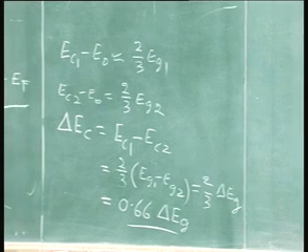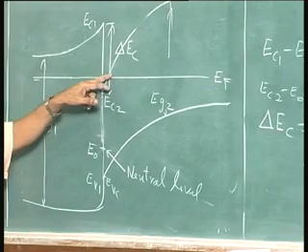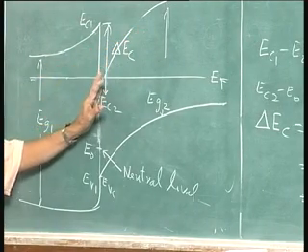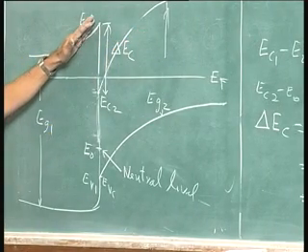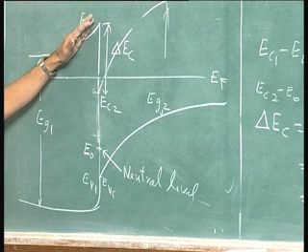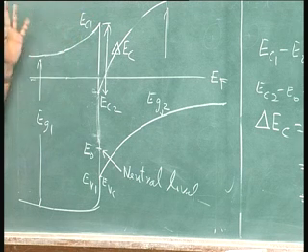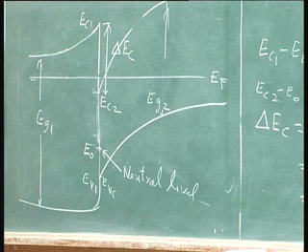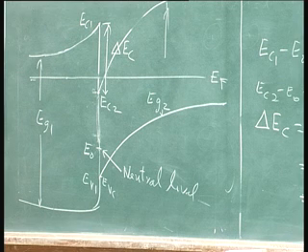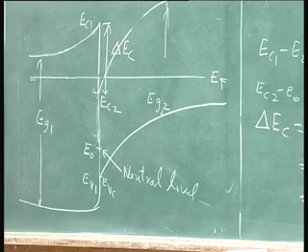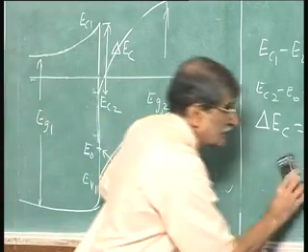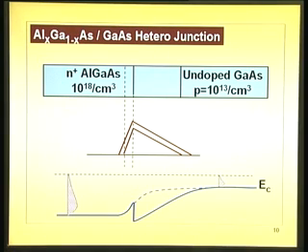What would have been the diagram? I would have got a depletion layer of a similar value here. What is the barrier here that is ultimately obtained? That is the built-in potential. And you can draw the same diagram that you have been drawing for the Schottky barrier, energy distribution of electrons. And here, energy distribution of electrons, minorities, till they match the difference has taken place.